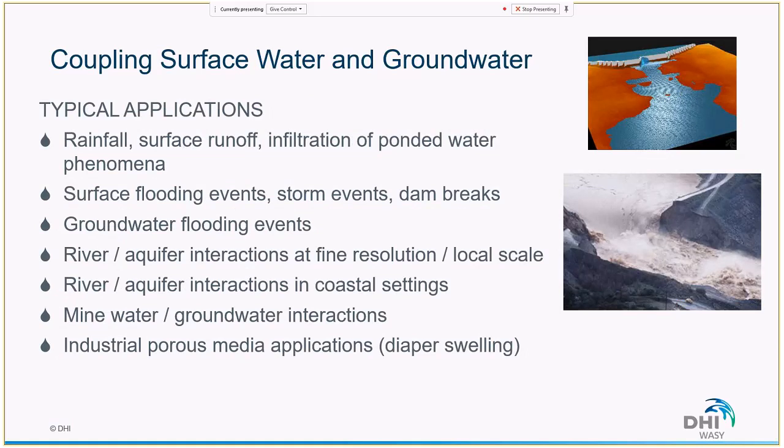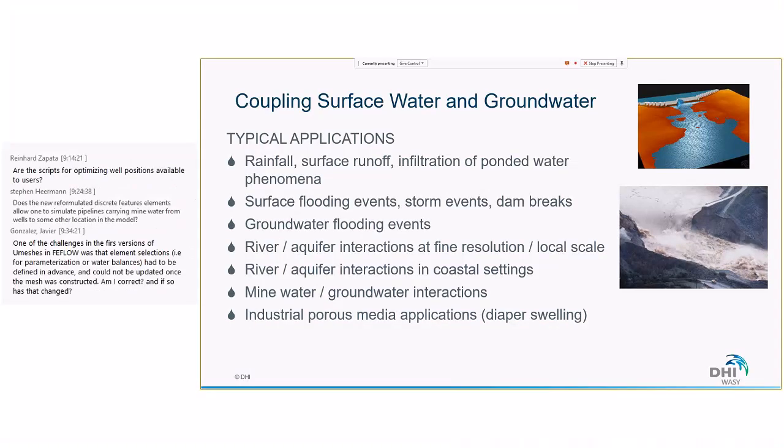This is the next part. What we are using here is our tool MIKE 21 Flexible Mesh. We can simulate complex scenarios of hydrodynamics in 2D, with the possibility of having a flexible mesh. It fits quite well the concept of FEFLOW. The coupling is really done quite easily. So you prepare your input data in FEFLOW. Input data is just one single thing, which is to prepare a discrete feature. So basically you select the area which will be set to the coupling.